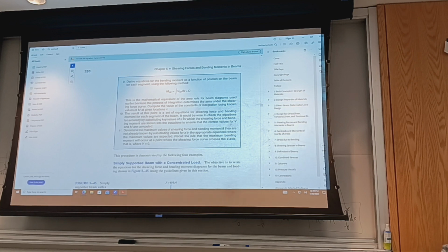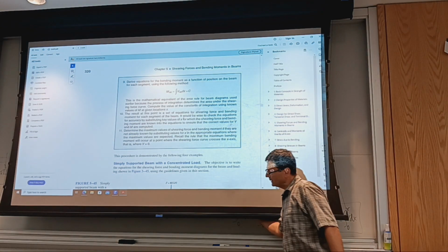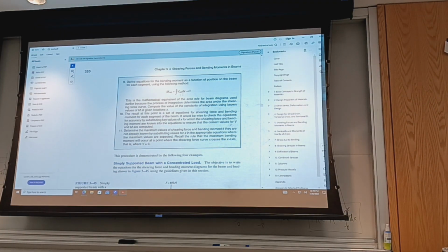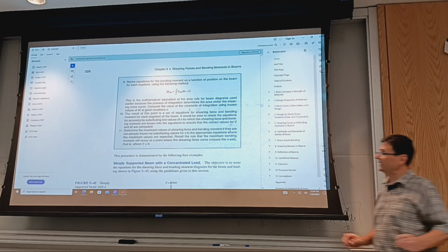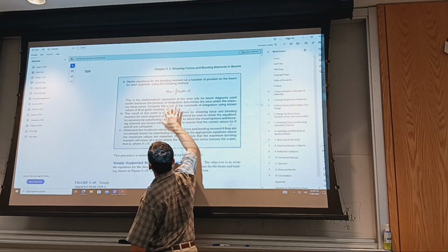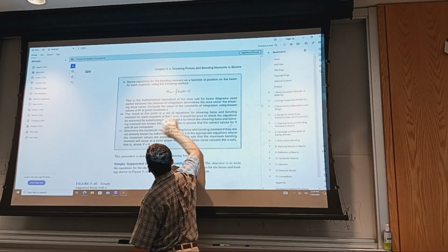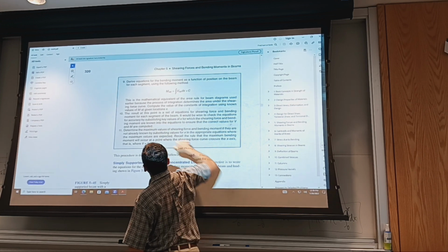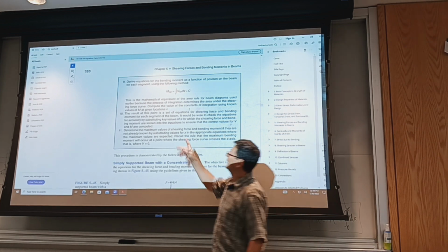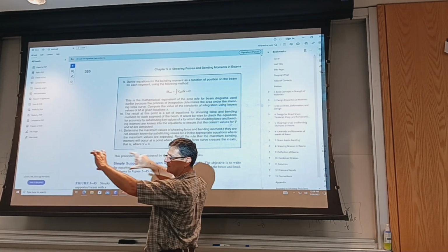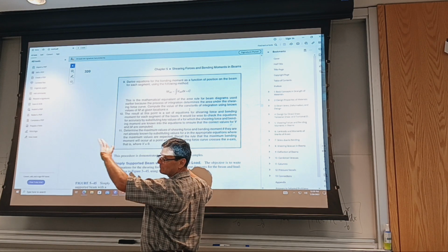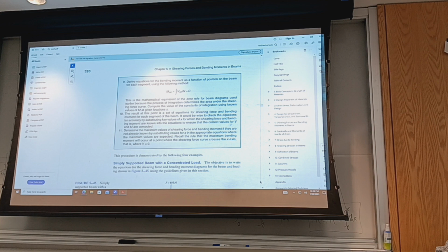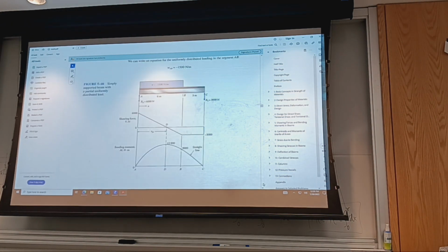What's boxed in, and the equations behind it, which I actually derived, are what I consider more important. We're going to see these equations taken two steps further, because the next one, integrating, gets you the deflection equation of the beam, and if you integrate one more time, it gets you the slope. And you can apply it, including for beams that have non-constant cross-section, like stepped shafts or shafts with taper. Okay, so I guess this is it.